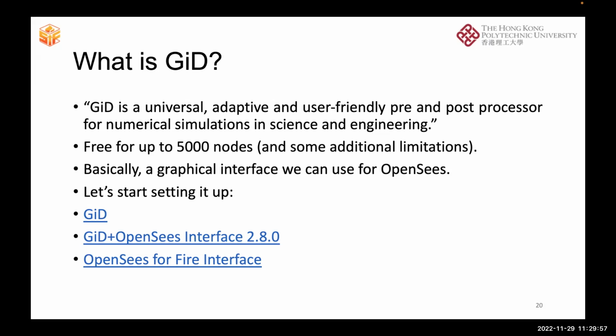We can customize the seed distribution and then have a dense mesh near the surface. But normally we don't use it. We just use a fine mesh for the whole section because it's computationally efficient, so we don't use a coarse mesh for the other part and a fine mesh for the surface. So far that's what we usually do, and that's why Amber did not use this kind of function.